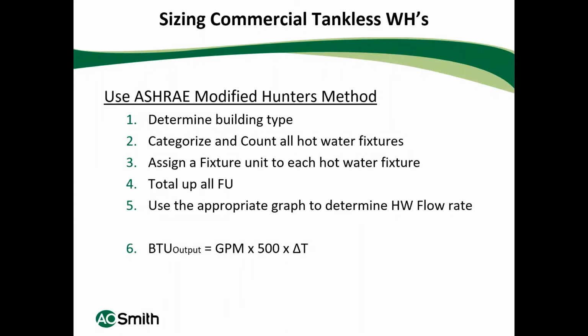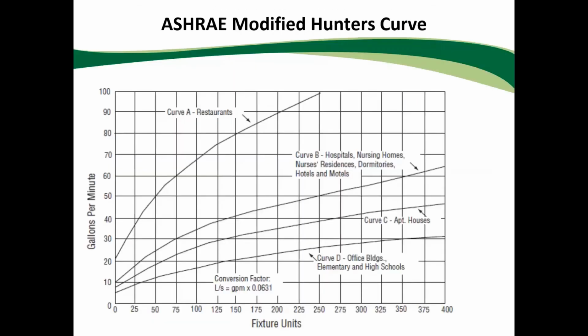If I was going to use our tankless heaters, I would be looking at here 1,350,000 divided by 200,000 BTUs each. I would need 7 units in that building to do that example.